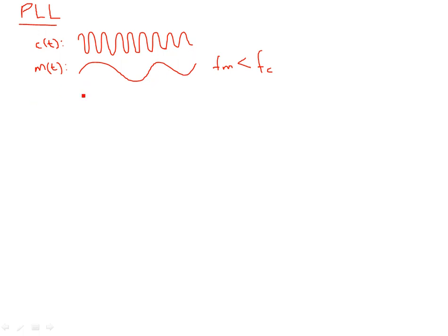So what happens is that in a typical FM signal, you have the instantaneous frequency being varied with respect to the amplitude of the message signal. So, for example, when the message signal has more amplitude, has more energy, the frequencies are more bunched together. They appear closer to each other. So it is a high frequency content over here. And then in this region in time domain, it is much more relaxed.